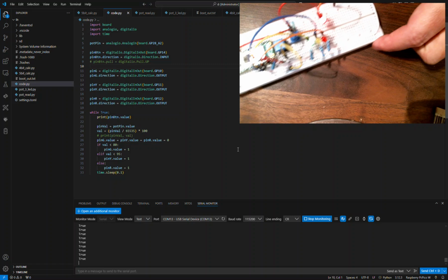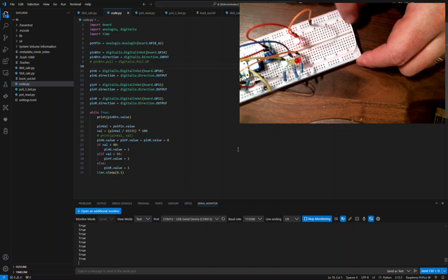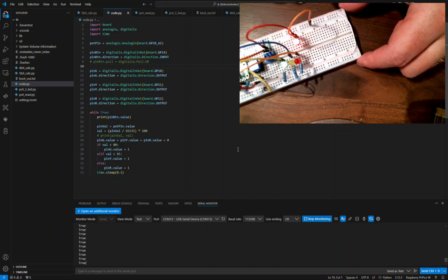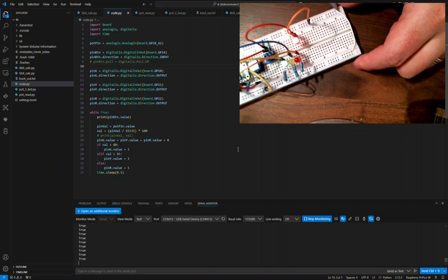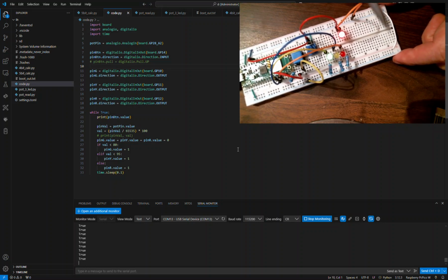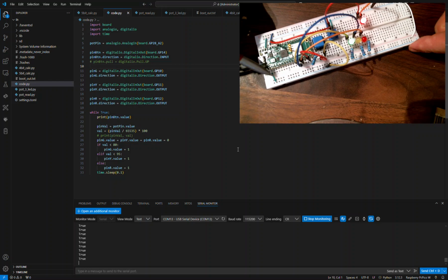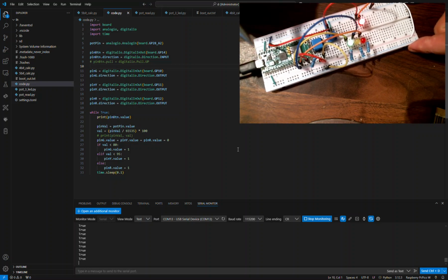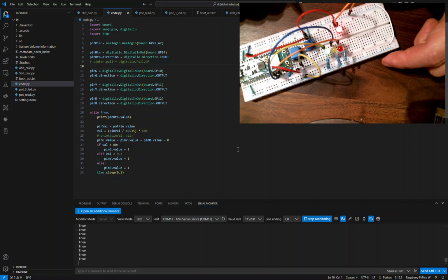All right. One thing I do want to point out is that I did add another connection from the plus side to the plus side, and that runs all the way back here to our 3.3 that's coming out of our board, so that both of these buses, we do have two different connections for ground, but then we're using the same bus for 3.3 volts.